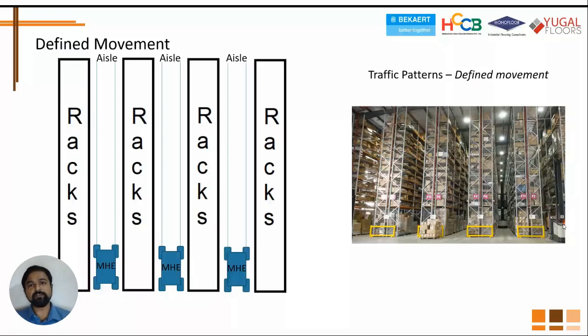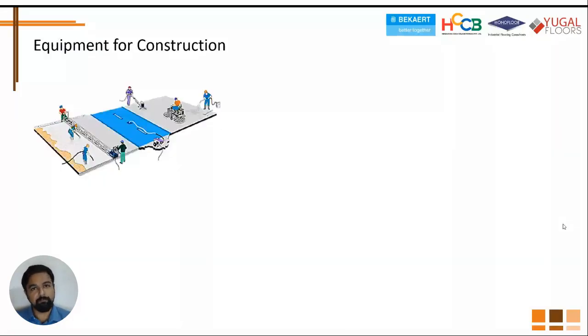The equipment used in construction has also evolved over time. We used to have a traditional beam screed, which was used for about 4 meters of panel width. Now the methods of construction have also improved. We started to move to a truss screed first, and then we also have laser screed.